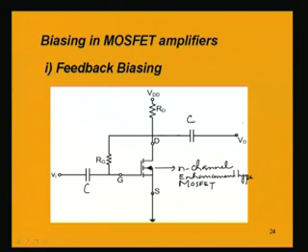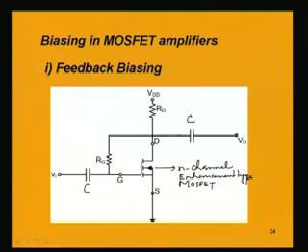The output is obtained at this end, and this voltage is known as VD, that is the drain voltage, which is the output voltage which should be amplified and not having any change in the shape as regards the input voltage. Input and output voltage must be similar in shape, although there may be phase reversal, but there should not be any distortion. So, we need to apply the input signal small enough to guarantee distortionless amplification.